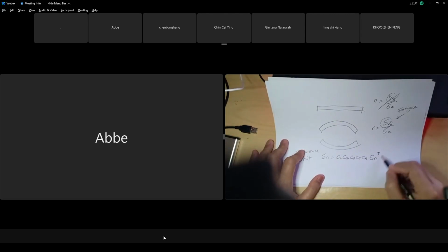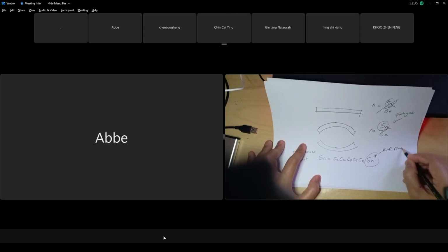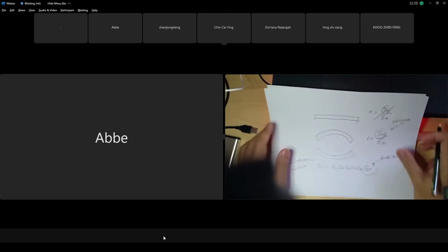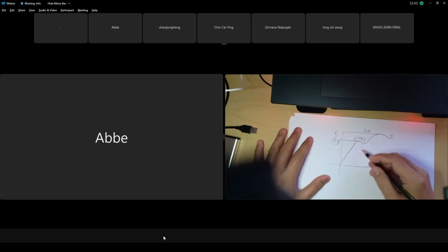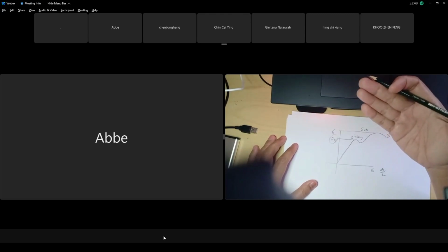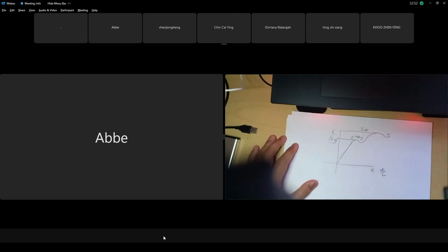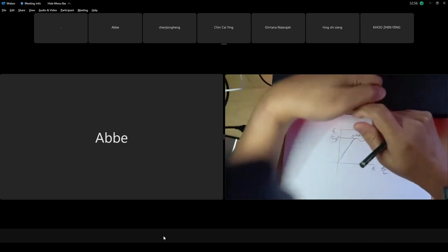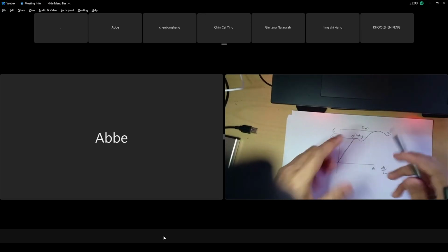SN prime is the endurance limit based on the RR Moore test. It is a standard done already by engineers a long time ago. Remember, for static loading, engineers already did it. For all materials they put the data, at the back of your textbook, the material properties, AISI 1040, you get the SY value because it was already done by engineers. For that material they made a universal tensile test, pulled it until they found the SY value.